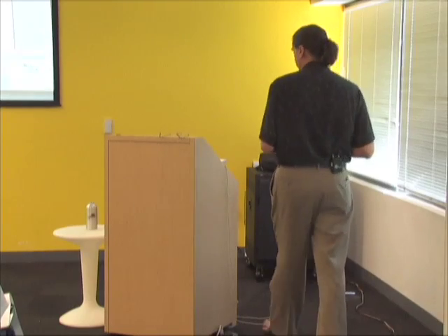And the other thing to remember, because we do this all the time at work, is large models are just a summation of small models. So we'll often take a component, save it out, and have somebody else go work on a different area of the project, and then pull it back in. You do have to be careful when you get really large models. Sometimes pulling components back into a model is painful or impossible.